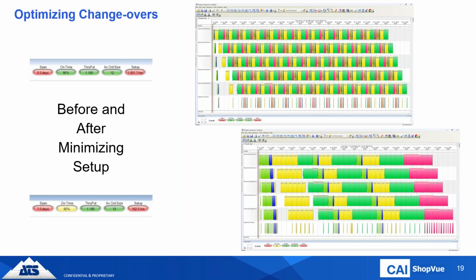So we'll start by looking at APS. Yeah, so this is a real quick, simple to grasp visual. This is, again, a schedule from a semiconductor placement facility. And so the idea here, and what you're seeing with these colors, is that grouping together by product families is the most efficient way, because when you went from one product family to another, it incurred a setup. So grouping them would minimize those changeovers.